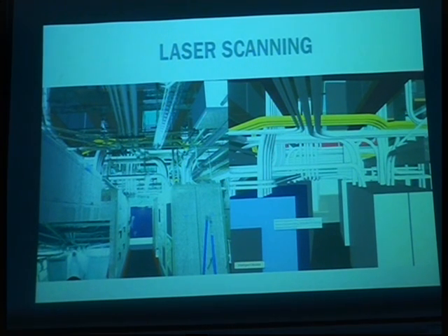They may, but most chances are they don't. It's been a historic building for I don't know how many years. So how can they produce drawings for an existing building? What we do is bring in our laser scanners, scan the building entirely, and then produce a model from which you can produce two-dimensional drawings and sections.